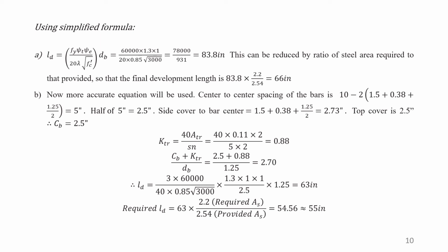We have to put in these different values, and Fy is 60,000. Because F prime C is under the root, we will never use Fy and F prime C in this equation in KSI. We have to put these values in PSI.